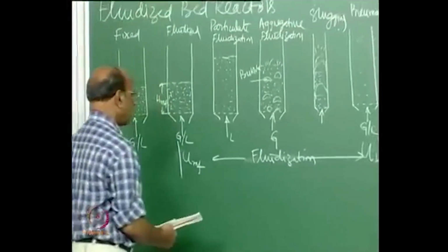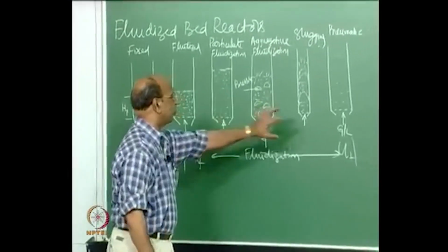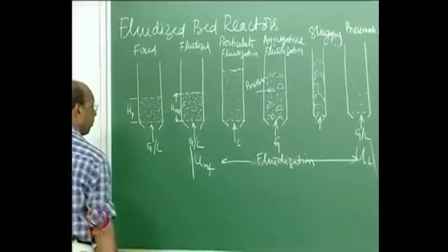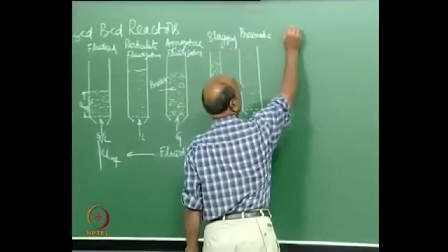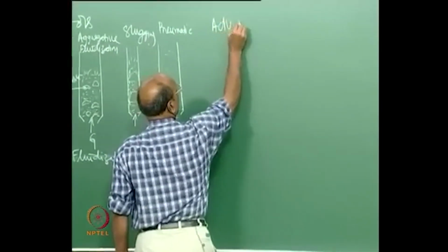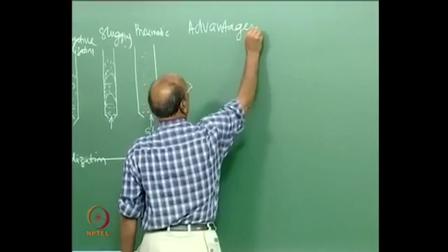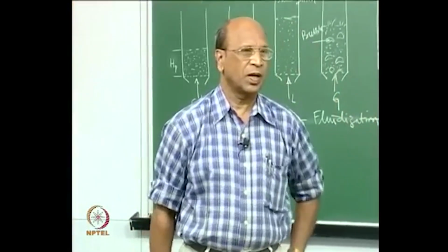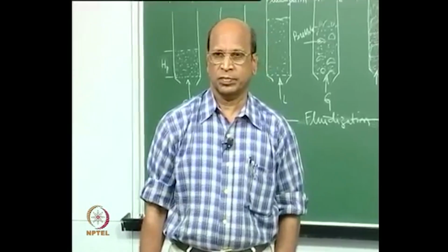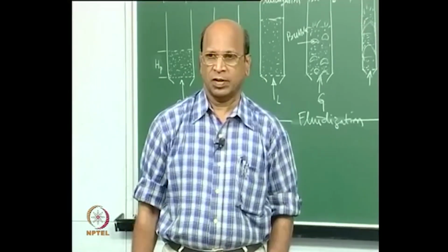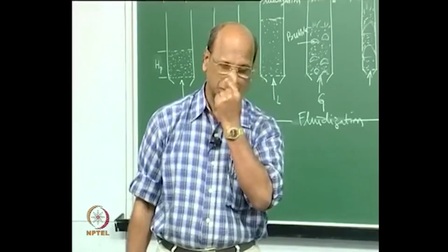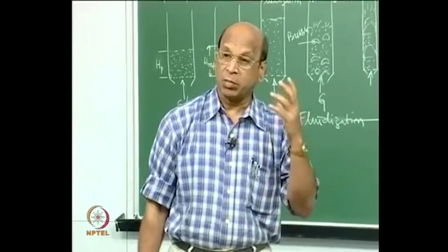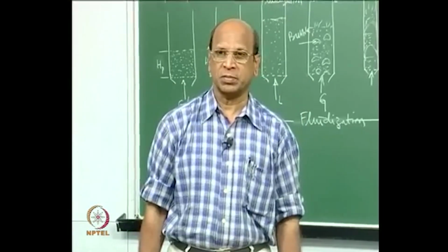Okay, good. So, now if you want to understand these fluidized beds, we need some parameters. But anyway, before that we will have the advantages and disadvantages. What are the advantages in using fluidized beds? Okay, good control of solids, that is one. And then excellent heat and mass transport processes inside the bed.